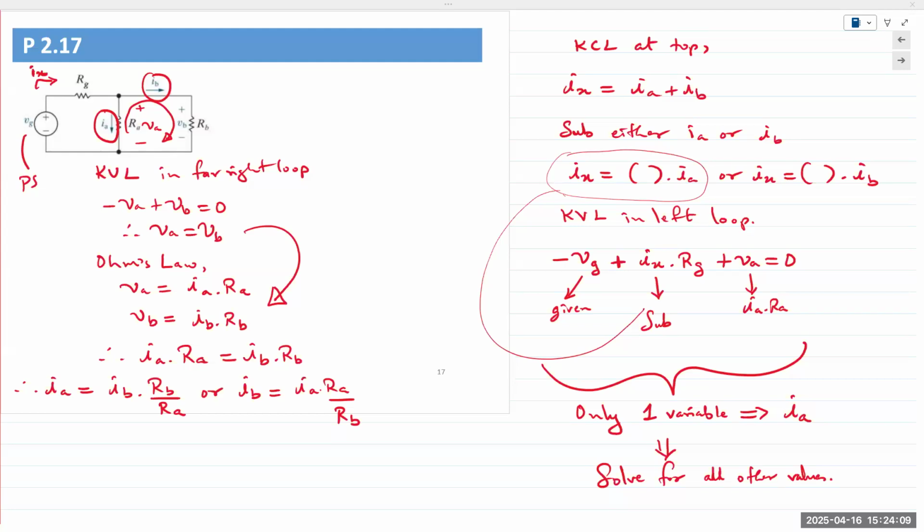Okay, do the steps make sense? Right? The whole point or the purpose of going through all of this is we want to solve for unknown quantities in the circuit. The unknown quantities are voltage, current, power, energy, etc. In this case, it seems as if there's no good way to start without solving for the resistors. But by an application of Ohm's law and KVL and KCL, we can apply them in any sequence we want. The point is we should solve for at least one variable.